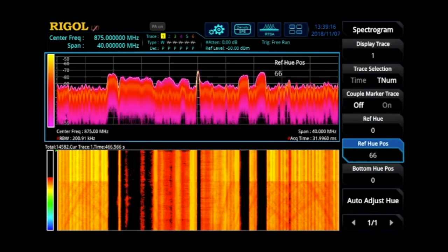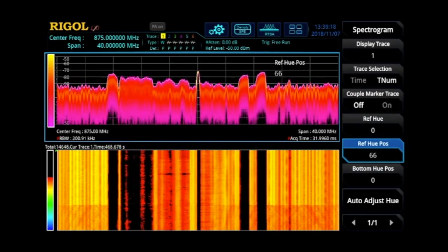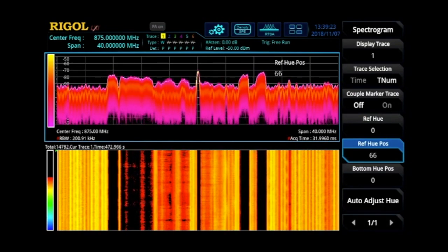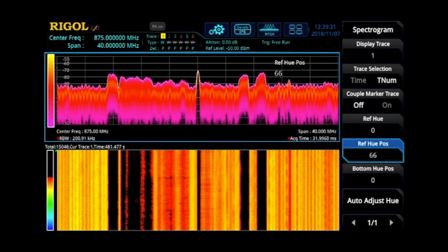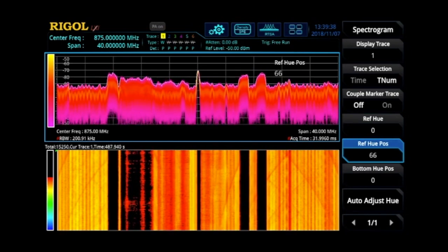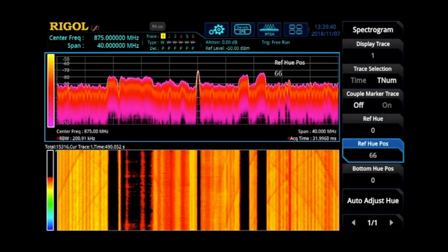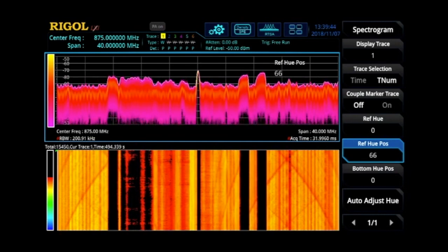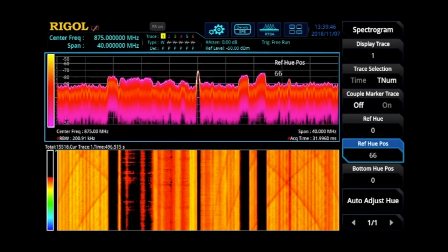We take a closer look, we can see right there a reset occurs and the power drops across this whole spectrum. Now over the next 30 seconds it builds again and resets, and this is a continuing, renewing cycle. If that was annoying us from a pre-compliance standpoint or from a functional standpoint, we could use this kind of real-time test with super accurate RF measurements to isolate the ultimate cause of that, what's causing that dithering frequency and that power building, and do something about it.